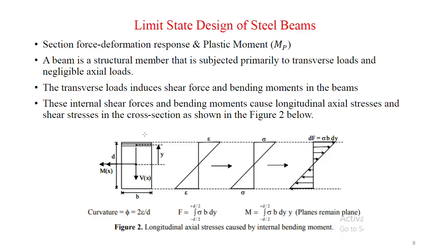Some of the concepts which we used to design a steel beam as per limit state design: you can see here section force deformation responses. We used to consider section force deformation responses, and the plastic moments which the particular beam will carry.